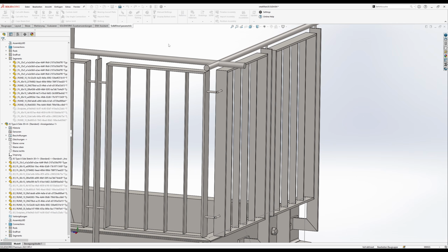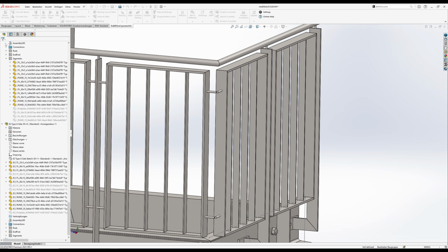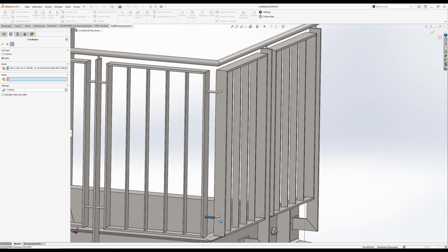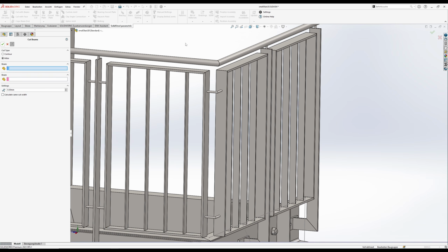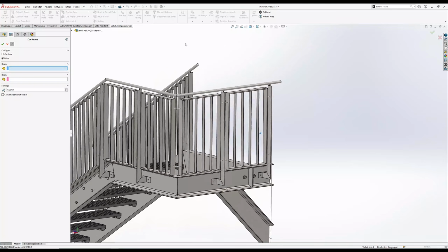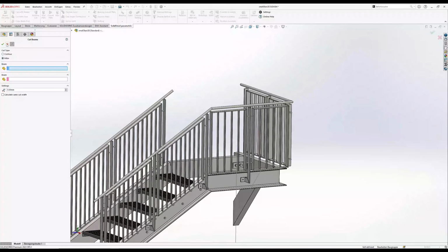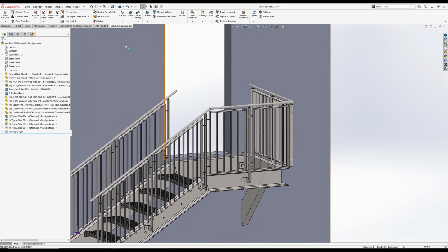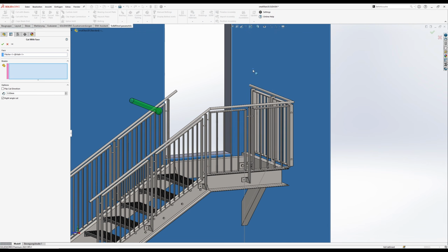Of course we could have mitered the boxes, those segments with the bars, but I'm going to do it this way. It's a matter of personal preference. Here I accidentally selected the wrong element. Of course these two are right. Another click on OK and the point is done. That looks pretty good. Let's unhide the wall again and quickly trim the back handrail with a face cut at the front of the wall.